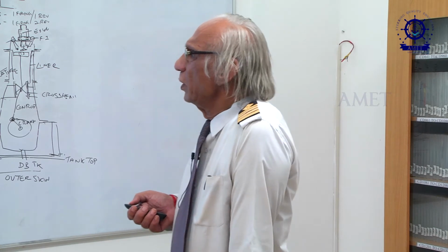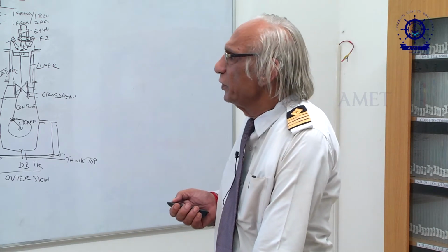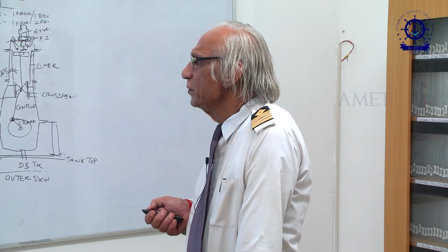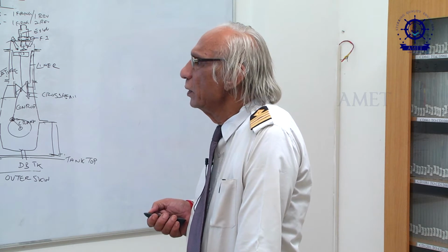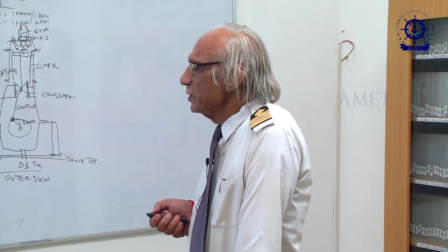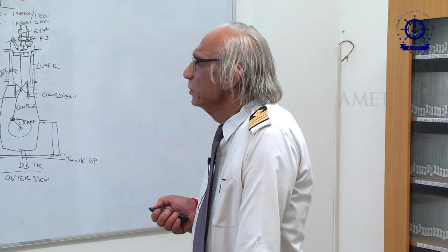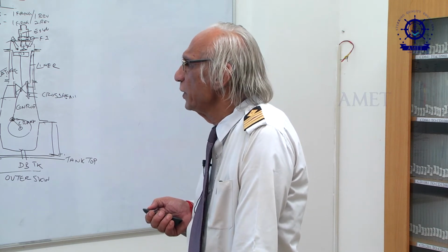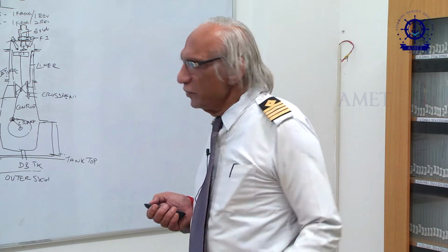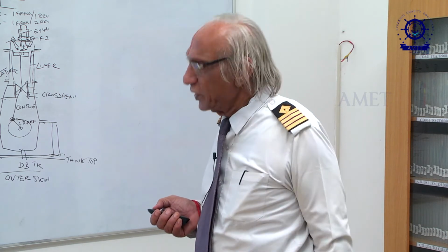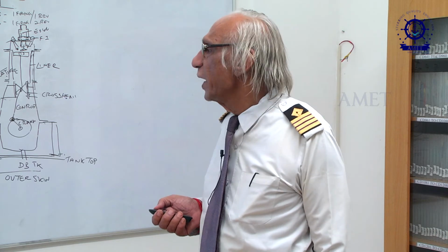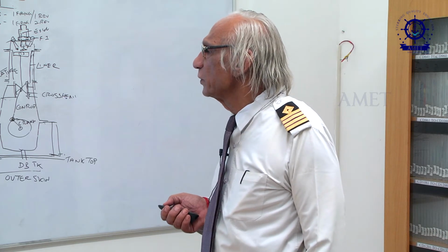The propeller is subjected to torque, which is part of the crankshaft, and there are hull deflections due to hogging and sagging. These are additional forces that the crankshaft bed plate is subjected to. What is hogging and sagging? When the ship structure is bending downwards, the deflection is downwards, and it is called sagging. When the deflection is upward, it is called hogging.